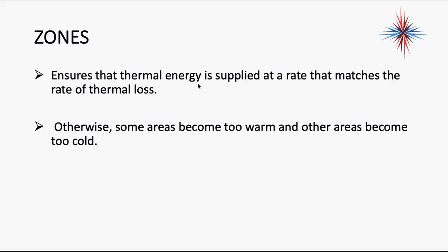Okay, we want to ensure that thermal energy is supplied at a rate that matches the rate of thermal loss. Otherwise, some areas become too warm and some areas become too cold. It's very important. Our heating system has to be designed to supply heat at a rate that matches the rate of thermal loss. That's why we're going through this whole exercise.